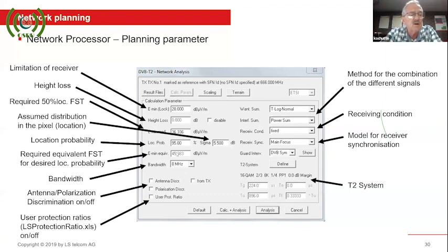Okay, so if we look at a typical network analysis tool, there are various things that will affect it, and this is apart from the previous slide we saw a while ago, where we looked at the pilot pattern and the QAM modulation, etc. So just with general RF, just looking at propagation, you will typically have a minimum usable field strength at which your receiver will lock.